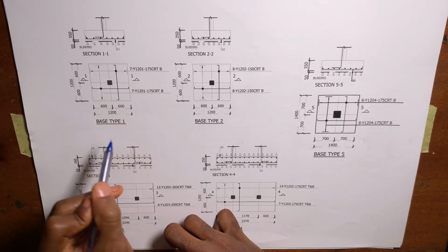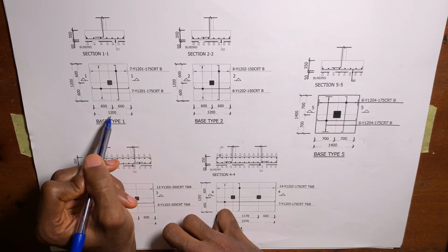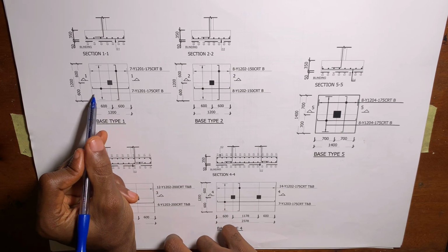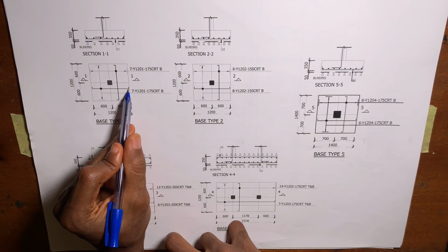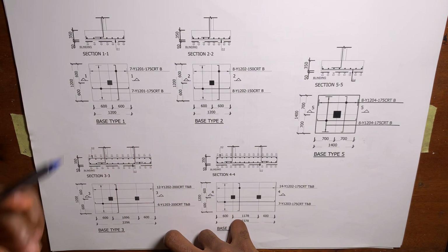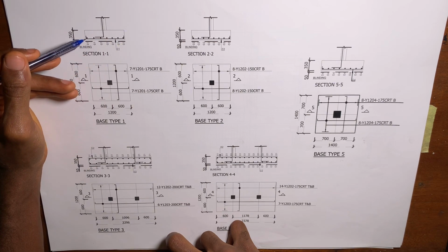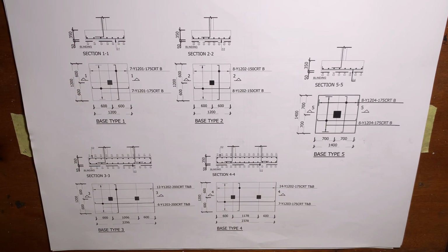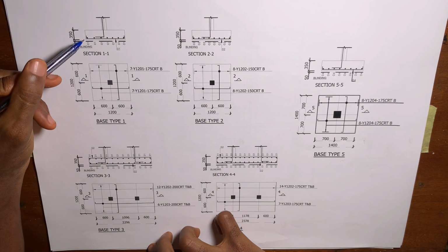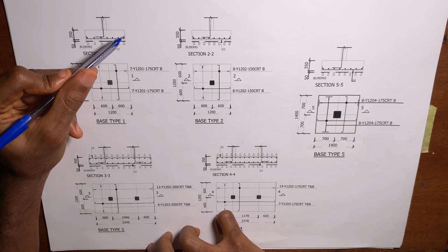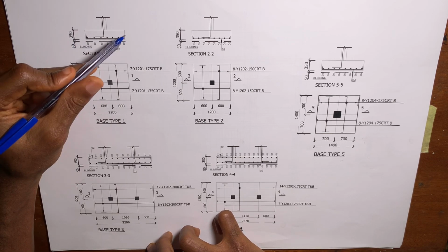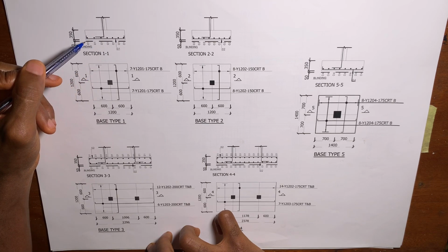So with that, since you know the length of the column base as 1200, you can now minus the concrete cover from both sides. It will give you the what? Length of this reinforcement. Now mind you, the additional reinforcement is bent at the top, right? As you can see in this section, if you've gone to site and you've seen when they are bending reinforcement for column base, you will understand what I'm talking about. So I'm not going to be leaving an addition for this bend at the two sides of the reinforcement.